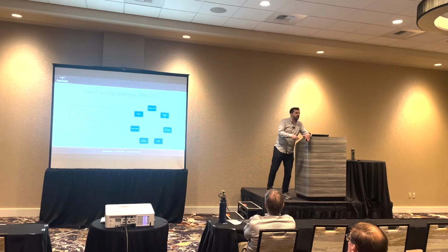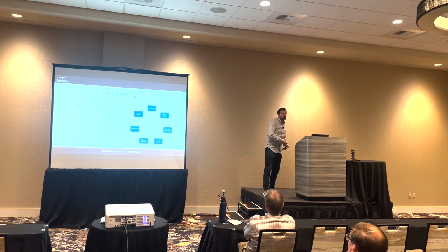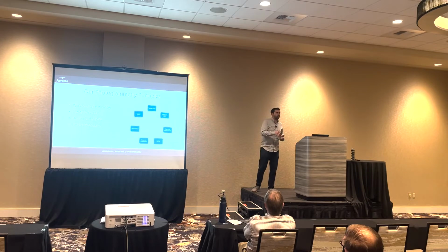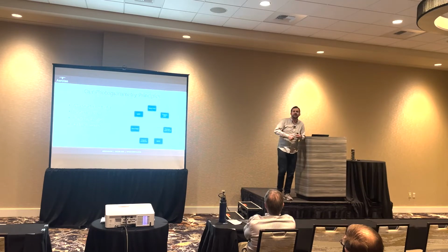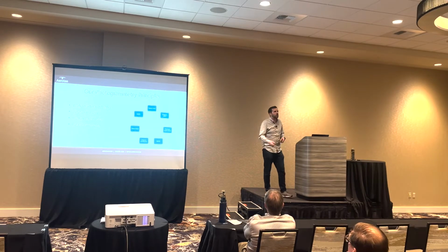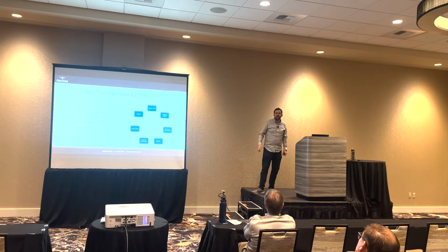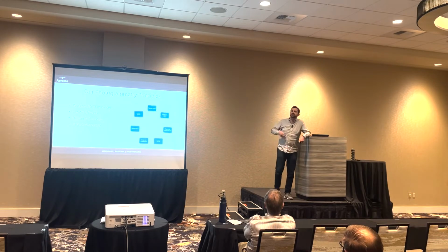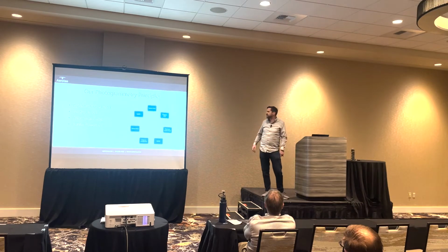Start with a really quick and dirty model. From a photogrammetric perspective, start with a very low resolution, initial ultra rapid processing just to validate your photos. Are there any major georeferencing errors, are there any coverage gaps, are the cameras calibrating at all, did someone leave the lens cap on, and things like that. You can do that in 5, 10, 15 minutes, and that's going to identify some of those biggest errors before you actually start increasing your resolutions, adding more computational power to it, and doing all of that. Go in an iterative process.